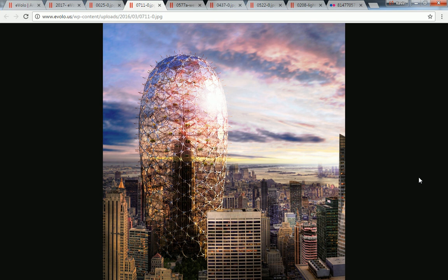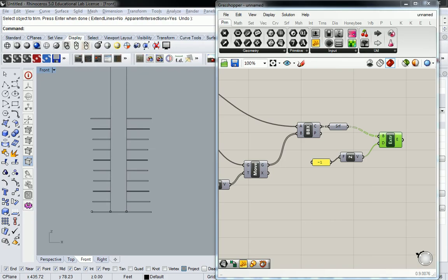You're going to go there and cut each one out that's not supposed to be there, or for whatever system you're using, whatever the case. You just need to have some foresight about what you're producing in the end, because sometimes you can leave it the way it is. You can let the floors penetrate through the elevator core and it doesn't matter. Other times, you want to make sure you cut it out.